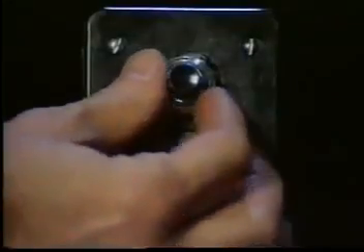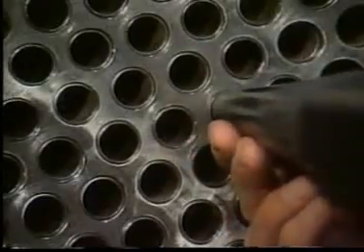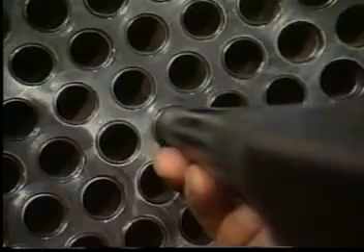For central areas, bring the ultraprobe sensitivity back up to normal. You may also increase the amplitude of the tone generator as the distance away from the vibration area increases. Use this method to check the integrity of the tube roll. Grossly thin spots along the tube will vibrate and therefore may also be recognized.